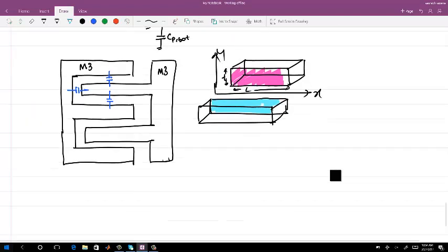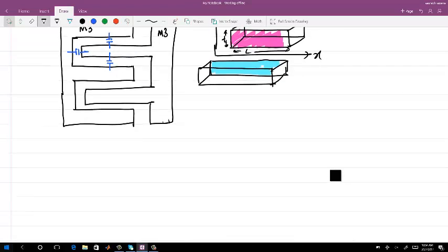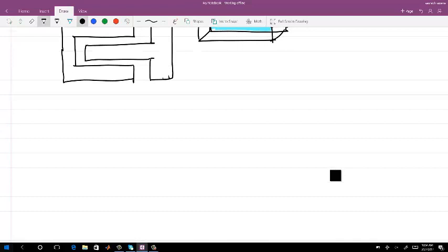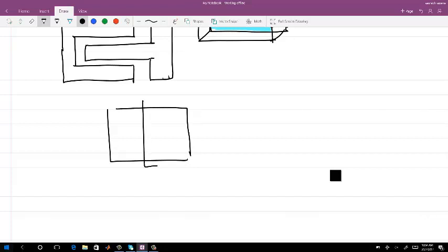And this kind of capacitance, we can use it here, but it can also be used if you want to increase the decoupling cap in your chip. Today we are going quite off the track, but if I want to realize a decoupling cap, quite often you use a MOS capacitor, which has a higher density. I have a MOS, and I short both the drain and source. So these drain and source are shorted, and then you have a gate, and you realize the capacitance between gate and ground.